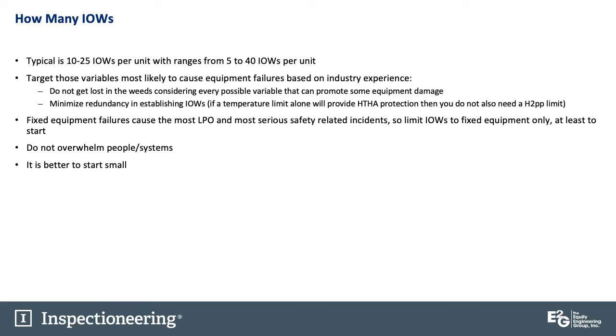I've already mentioned this. Fixed equipment failures cause the most LPO and most serious safety-related incidences in refineries. So limit IOWs to fixed equipment only, at least to start. Don't overwhelm your people or systems. It's better to start small.